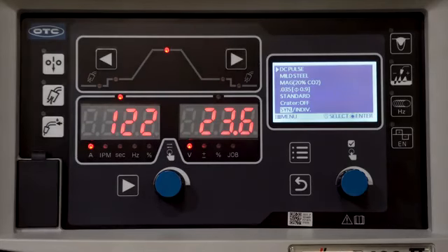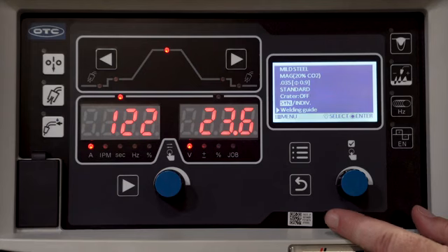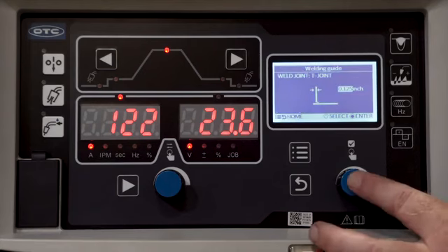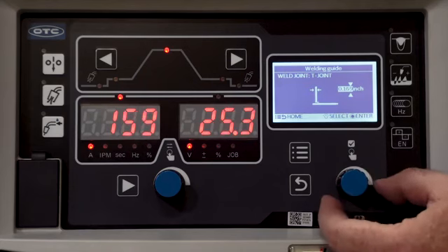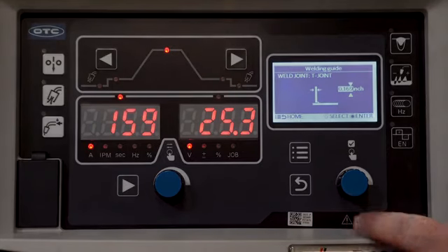One new feature on the Welbee II is our built-in advanced welding guide that allows you to easily select your welding parameters based upon your joint type and material thickness. To access that from the home screen, scroll all the way to the bottom to Welding Guide and press Enter. Here we can select the material thickness, and you notice as I change my material thickness, my weld settings are automatically changing.